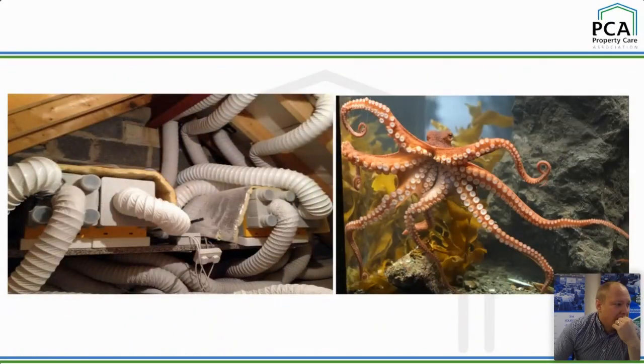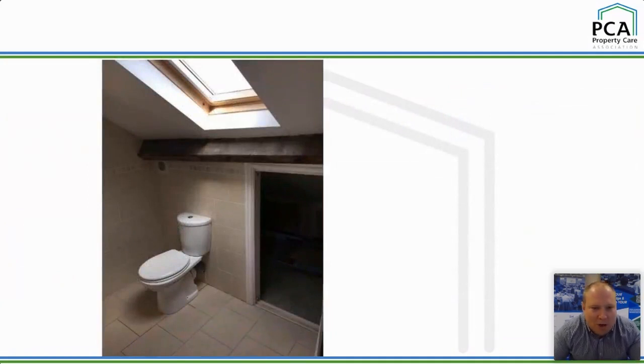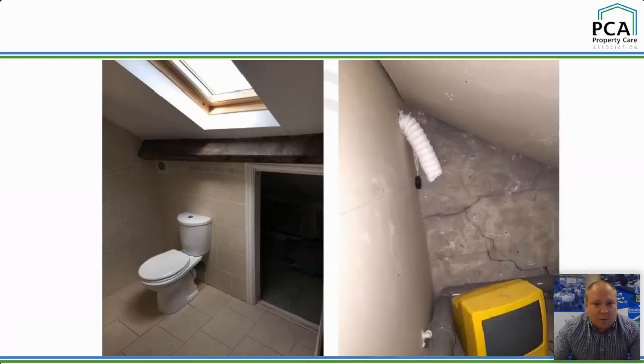So this is an MVHR unit, and it's meant to be the Rolls Royce of installations, but look at the problems that's going to cause. Pretty poor. And one of my personal favourites, this one. You can see that extractor fan, fairly low level, just because of the roof line. Ducted out there, but always check where it's going, because this is the other side of the plasterboard. So, I mean, it says it all, doesn't it? Why would you even bother, given the problems that's going to cause?